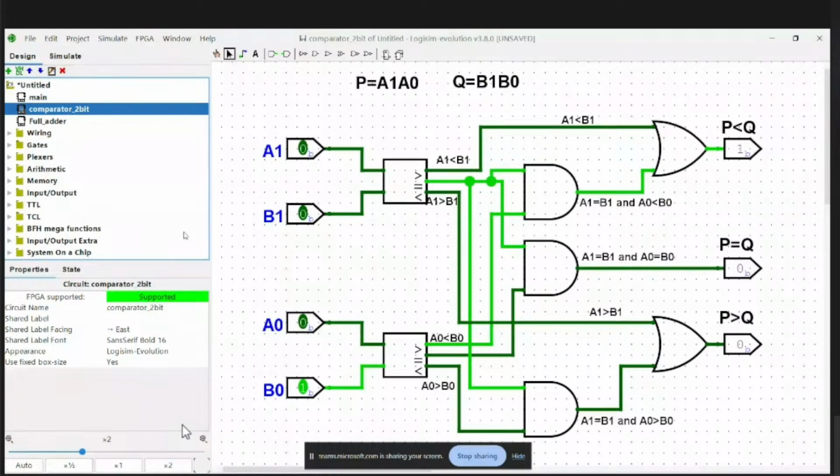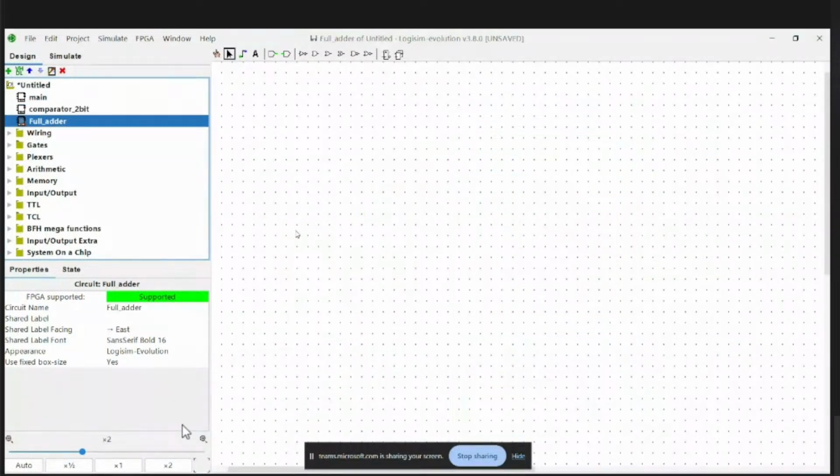using. And yeah, let's go on with our full adder circuit. So we had our expression for sum as A XOR B XOR C, or like X XOR Y XOR Z, and the expression for the carry as AB plus C into A XOR B, which is nothing but XY plus Z into X XOR Y. So we need 3 inputs first. So let's start with 3 inputs.